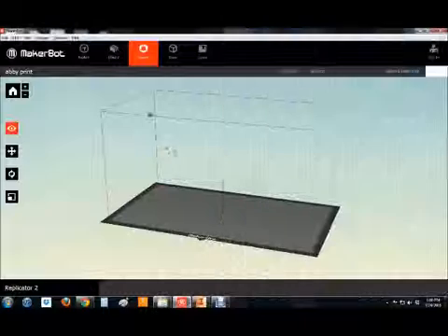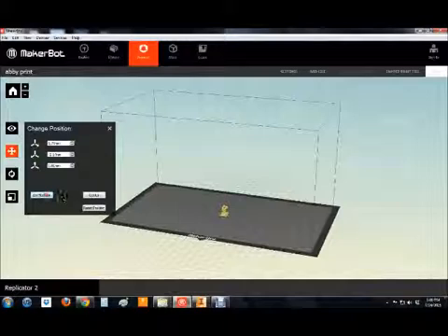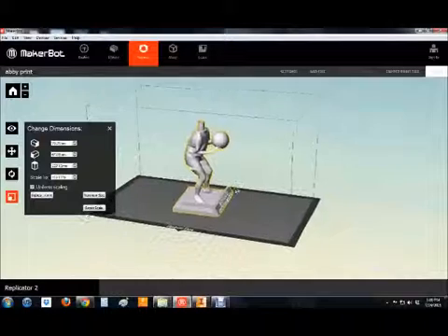And I should undo that. Oh, it doesn't matter, I guess. So we're going to select the object, and I should have said move to platform, and I said keep position. It's not that big a deal. I'm just going to go to this and go on platform, which will kick it up. And now we have to raise the size of it. So I'm going to click 5, since that's how tall we want it to be. And then I'm going to click inches to millimeters, and so that will make it 5 inches tall.